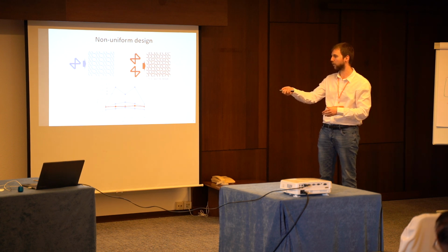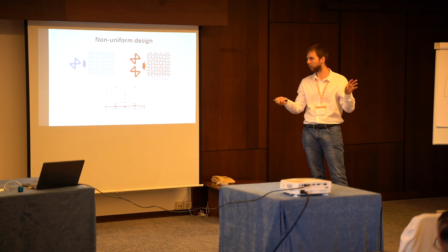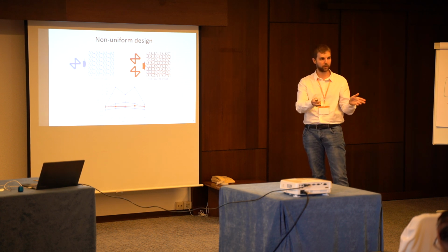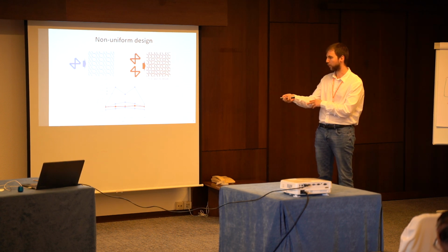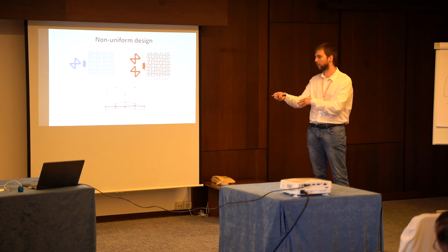If you consider different tessellation numbers, like 1 unit cell, 3 by 3, and 10 by 10, with periodic boundary conditions, you obtain a decreasing performance in the basic design, the blue curves. You see that buckling strength decreases, while for the non-uniform design, it remains invariant with the loading direction.